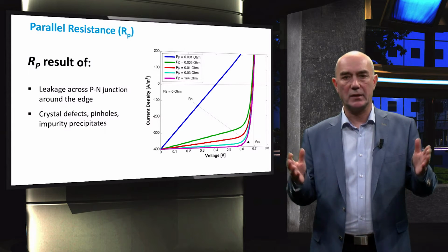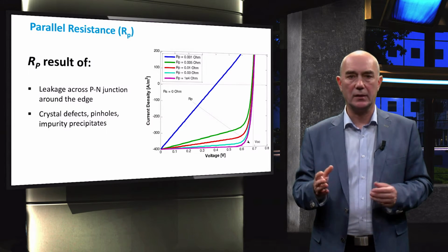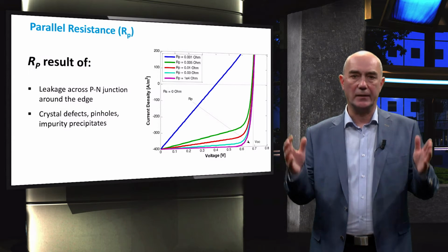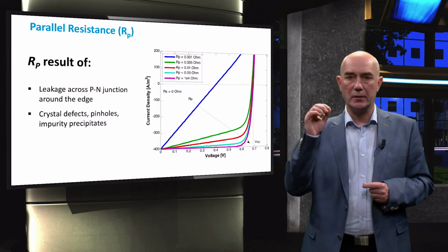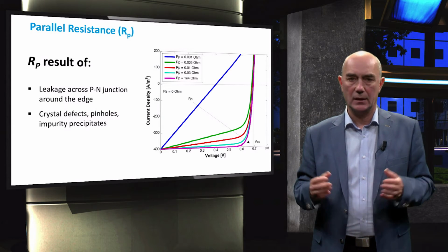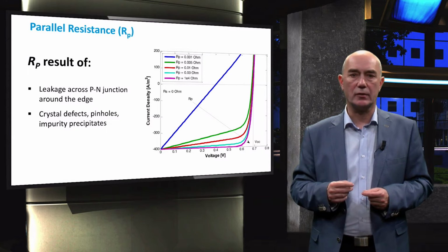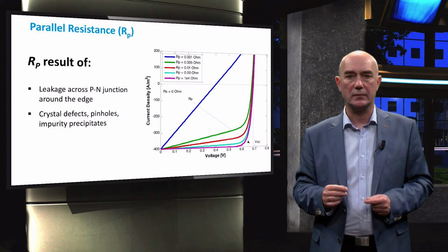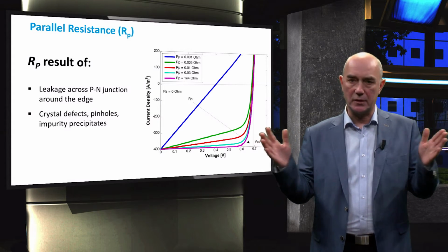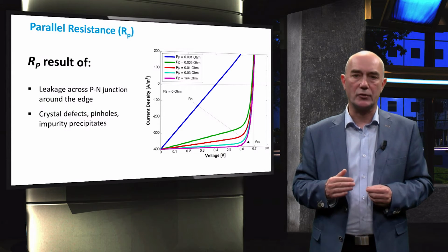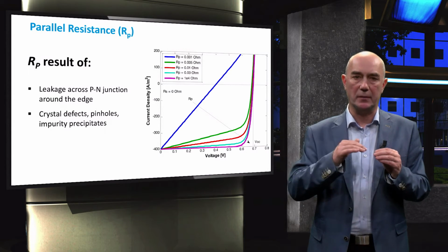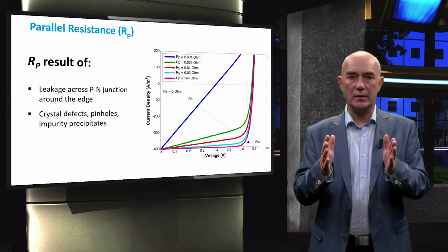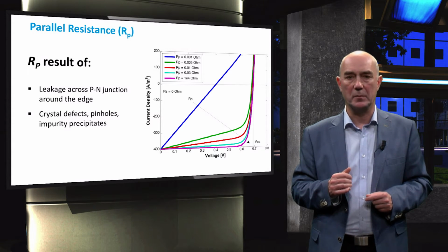The effects of the shunt resistance on the JV curve and fill factor are illustrated in the figure. The JV curve of an ideal solar cell is represented by the purple curve in the figure. The shunt resistance in an ideal solar cell is infinite, so that there is not any leakage of photocurrent. If the shunt resistance is reduced, we see the slope at the short circuit current density becomes steeper, and the maximum power point is reduced. The smaller the shunt resistance, the smaller the fill factor will be.